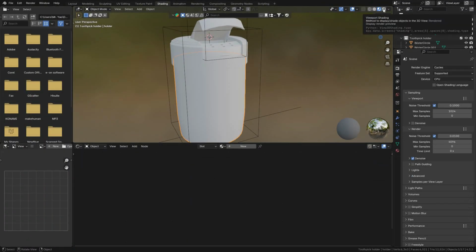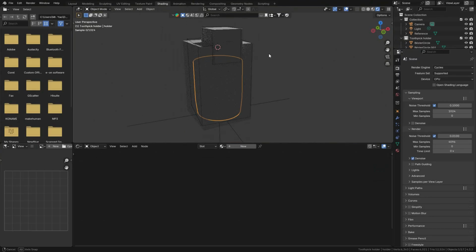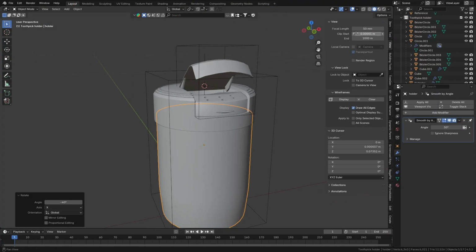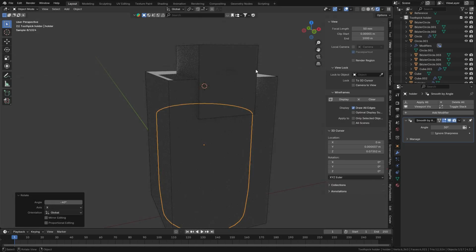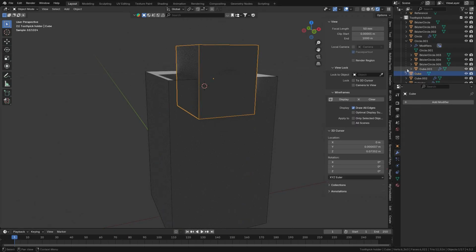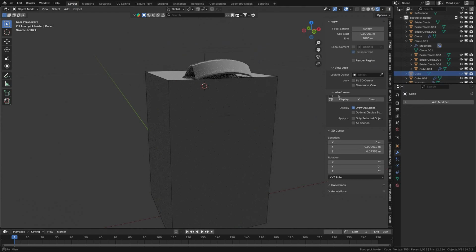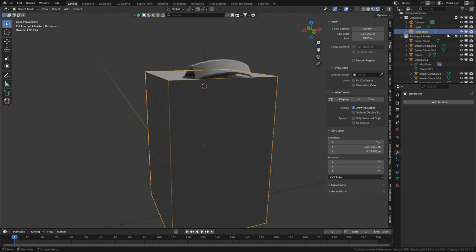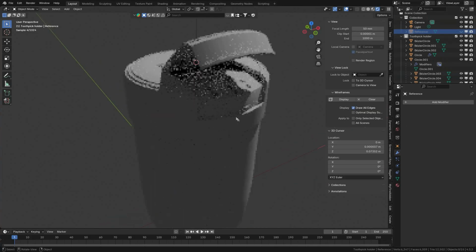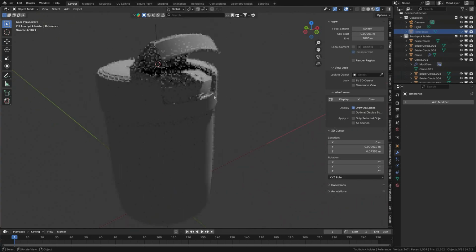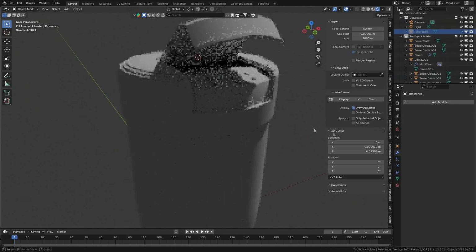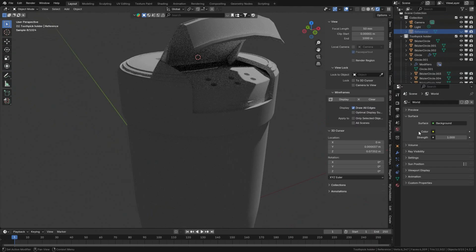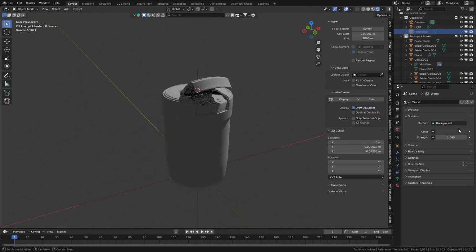And now to view it, we'll go back to our layout, go to render preview. Now you see that when we enter render preview, we get these blocks, which are basically the wireframes that we created. We can simply hide them by clicking the eye button here, as well as for the reference, just so that you are able to see our model.